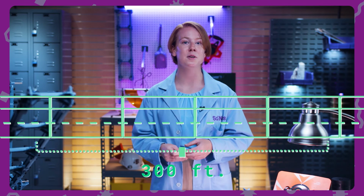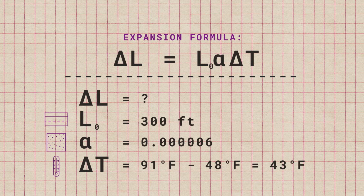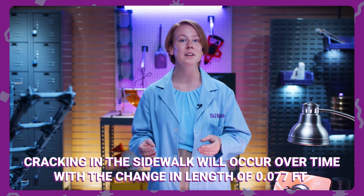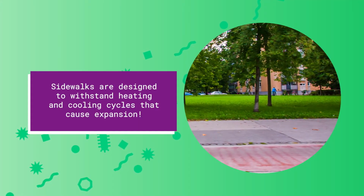Let's consider a sidewalk that runs for 300 feet. The average high temperature for Florida is 91 degrees Fahrenheit, and the average low is 48 degrees Fahrenheit. We'll note that the coefficient of thermal expansion for concrete is 0.000006. That's 5 zeros. If we plug these numbers into our formula, the change in length of the sidewalk would be 0.077 feet, which is nearly a whole inch. That might not seem like a high number, but cracking will occur in the sidewalk if it spans 300 feet. Expansion joints are purposefully put in sidewalks so that cracking will not happen so easily.